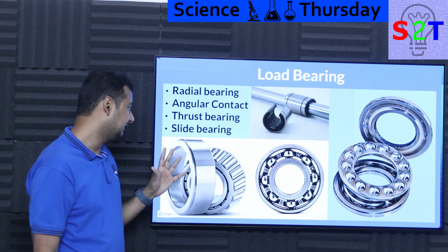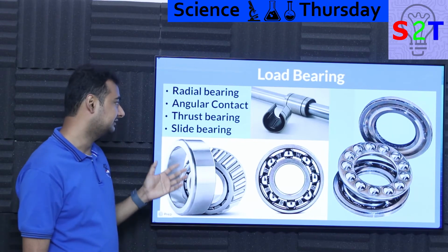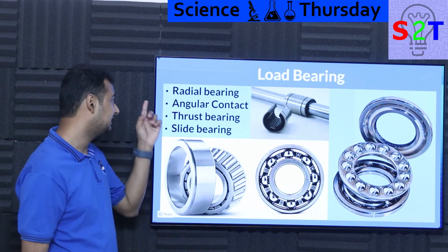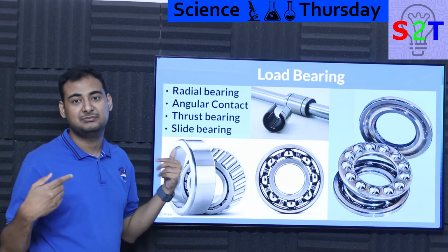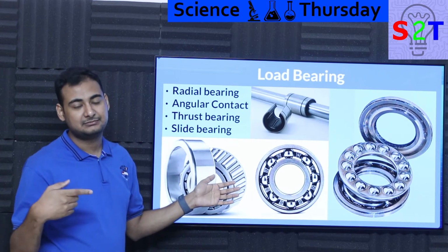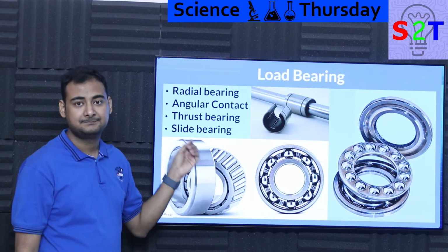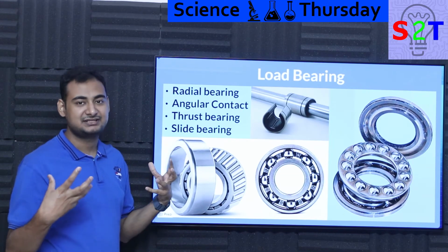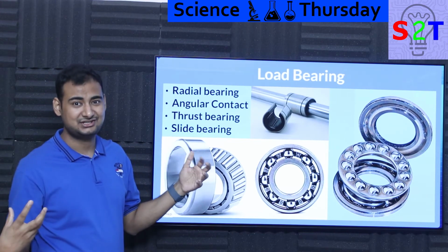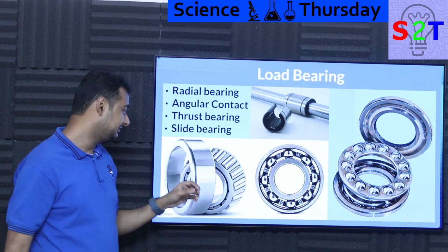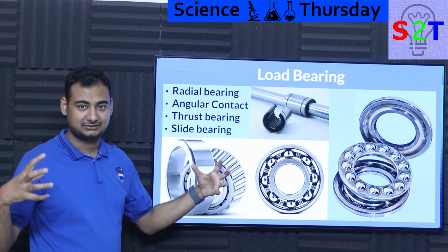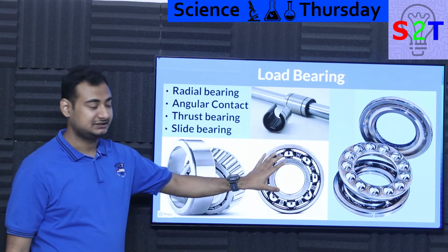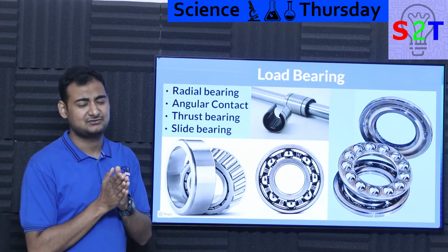So that's how we have the primary configurations of bearings. You have radial, angular, and thrust bearing. Or you could have a scenario where you utilize all of these, because each of the bearings has its own benefit. For example, the least amount of rolling resistance is found in radial bearings, the most amount of stability is found in angular bearings. So let's say you are talking about a rocket engine's turbocharger, you could have angular roller bearings on the ends so it does not vibrate laterally too much, and basically normal rolling elements, because it's very space efficient.